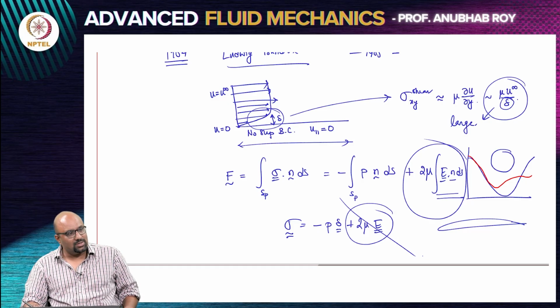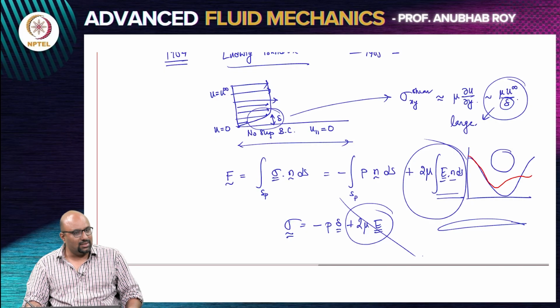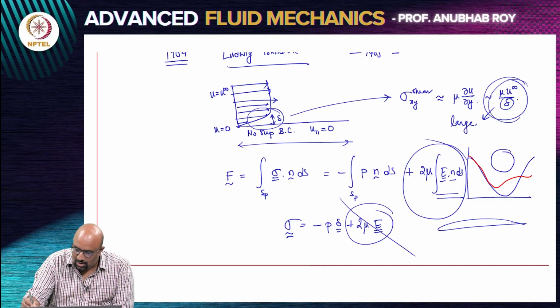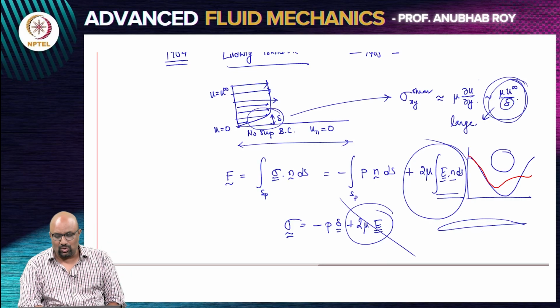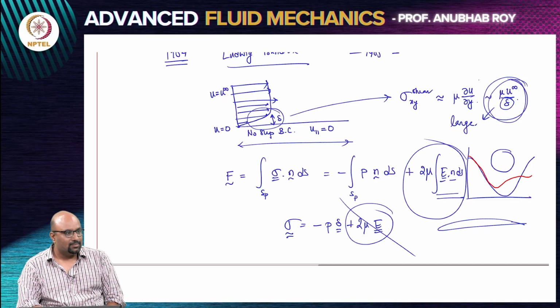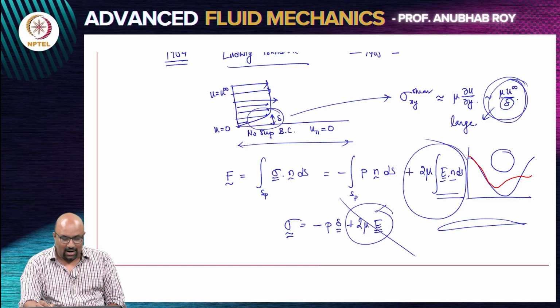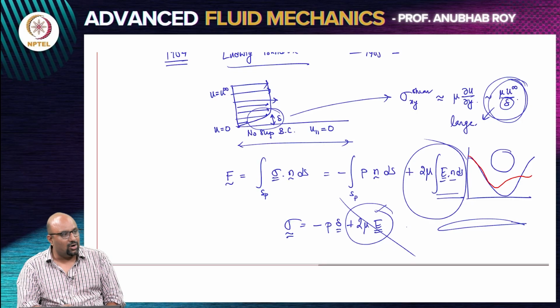Prandtl's insight was, if there is a high speed flow going past a surface, the fluid has to adhere to the surface and then the fluid gets a short transition region over which it transitions to the exterior flow. So now if you work this out, you get a shear stress which is not guaranteed to be small. It can in fact be large. And thus this part which was earlier erroneously dropped needs to be brought into the picture. And this is exactly how he motivated the problem.